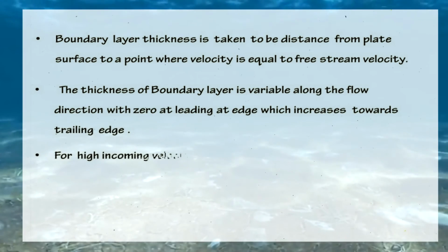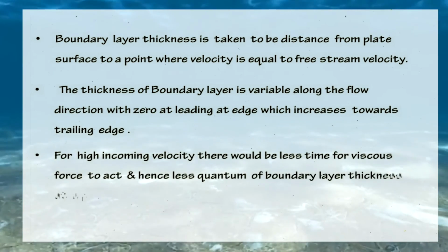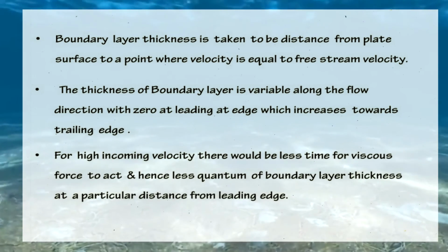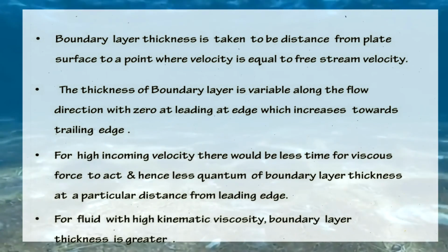For high incoming velocity, there would be less time for viscous force to act and hence less boundary layer thickness at a particular distance from the leading edge. For fluid with high kinematic viscosity, boundary layer thickness is greater.